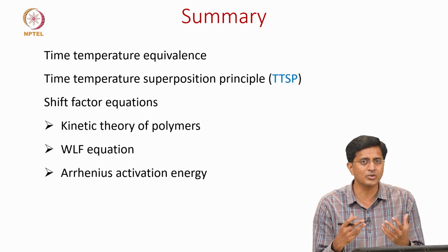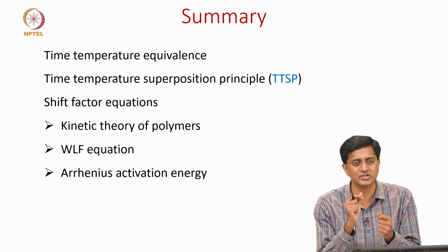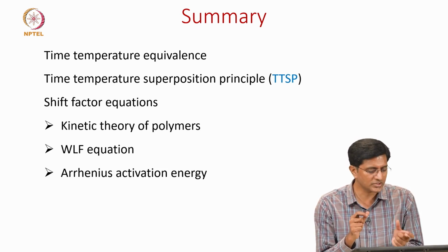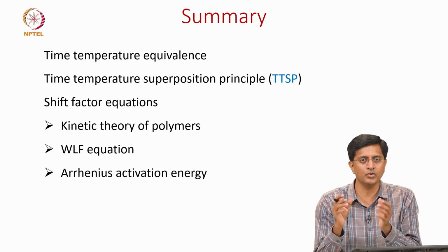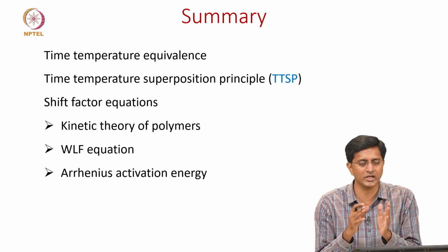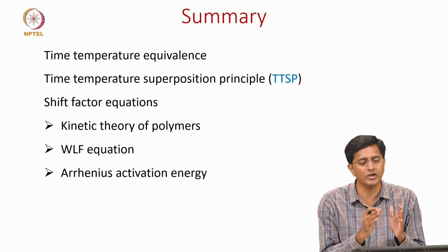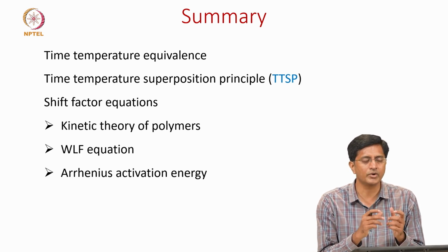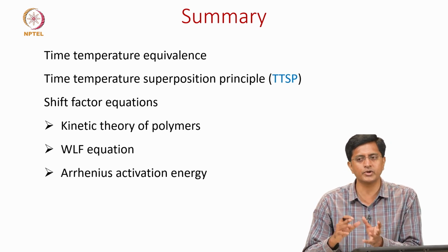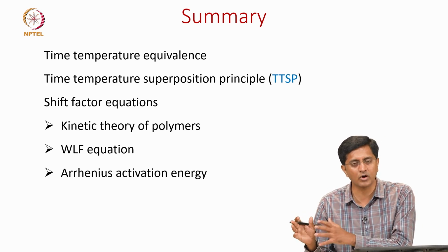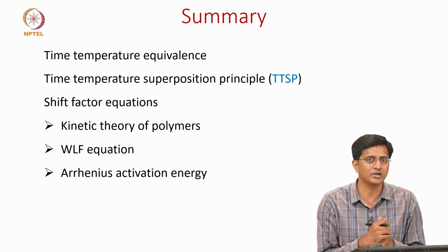It is very hard to design an instrument where you can really capture the behavior in a fraction of a second. But using time-temperature superposition, we can shift to low times, meaning you do the tests on the order of minutes like we showed in this video, but using that data you can shift it to very low times and predict how the polymer behaves. So, it is not always that we use this to predict how the polymer behaves at long times, but we also use it for very short times or very high strain rate events.